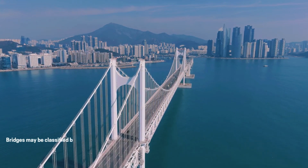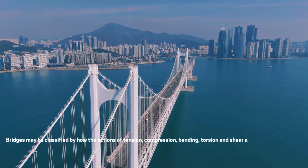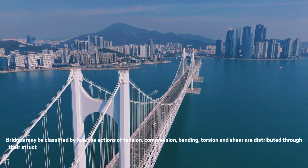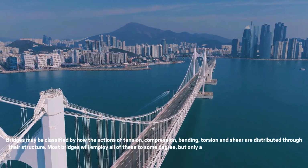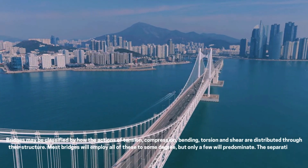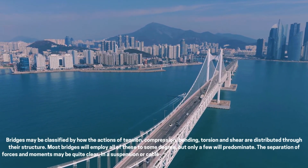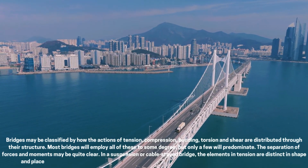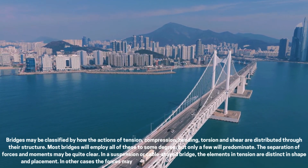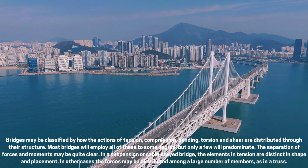Bridges may be classified by how the actions of tension, compression, bending, torsion and shear are distributed through their structure. Most bridges will employ all of these to some degree, but only a few will predominate. The separation of forces and moments may be quite clear. In a suspension or cable-stayed bridge, the elements in tension are distinct in shape and placement. In other cases, the forces may be distributed among a large number of members, as in a truss.